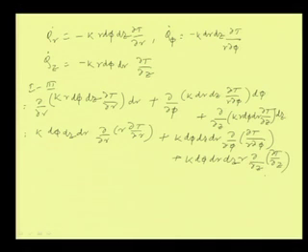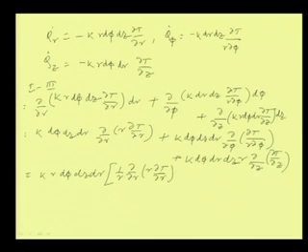So, we can write it like this: k into, if I take one r also here, r d phi dz dr, then we can write 1 by r del by del r of r del T by del r, plus, since we have taken one r here, it should be 1 by r square into del square T by del phi square, plus del square T by del z square.